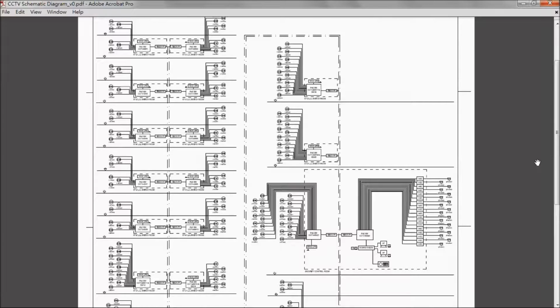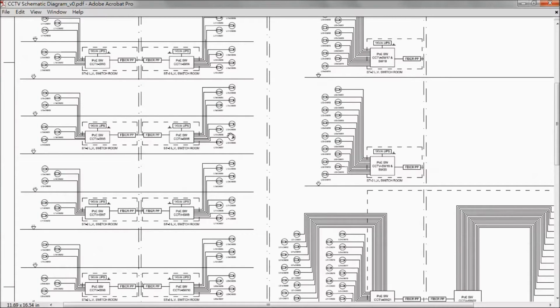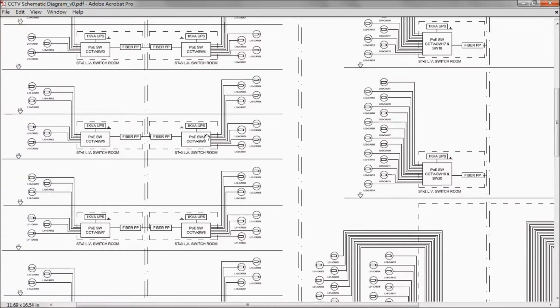Here is one of my job references to build a CCTV system for a hotel in 2012. There are actually more than 170 cameras throughout all the hotel buildings, in each floor, in the corridors, in all the common areas, including restaurants, concierge desks, and amenity floors such as gym rooms and swimming pool. The lift camera will also be integrated into the CCTV network. Most of the cameras are digital, and they obtain the power from the PoE switch.